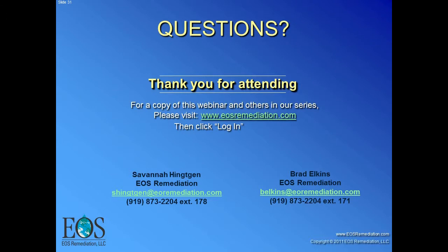If an aquifer is already highly anaerobic, is it necessary to add hydrogen donors? Well, essentially what you're asking is monitored natural attenuation versus enhanced remediation. If the aquifer is highly anaerobic and there are already lots of electron donors there, then obviously you don't need to add them. But if it's highly anaerobic and there's lots of electron donors, you probably don't have much of a plume. So it's essentially already going away all by itself.